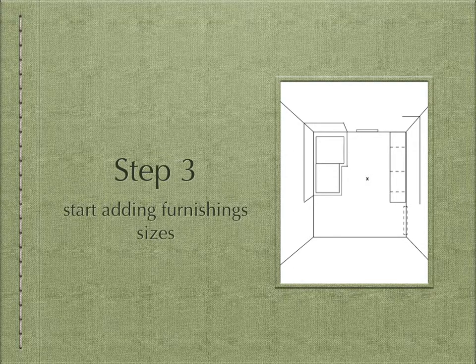In fact, many times I just use a 1 to 50 scale, but in actual fact, if you get used to it, you won't even need to worry about a scale. It's very simple. So use a measurement if you want to, just to get yourself familiar with the technique, but maybe a 1 to 50 if you want to. But obviously the bath height is something like about 500, 600 max, and of course the unit height in a bathroom is around 800 millimeters, so that's what we're looking at. And the variations that you get in ordinary perspective aren't that fussy in a bird's eye.